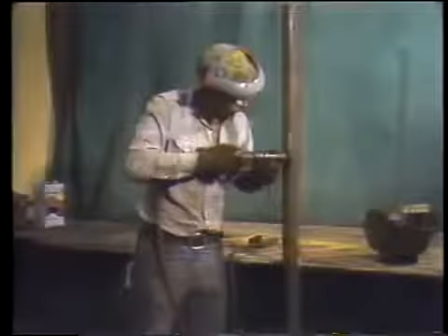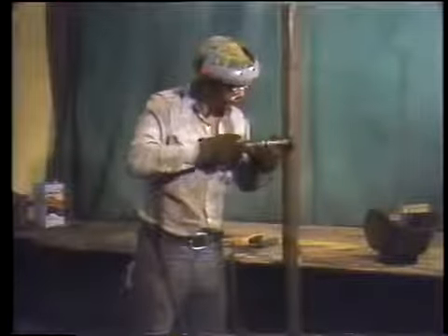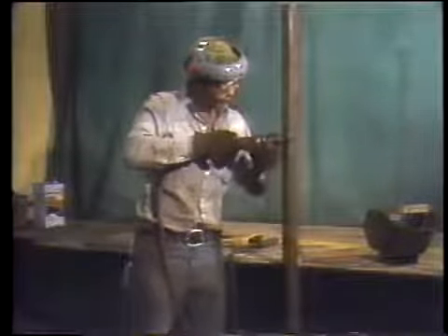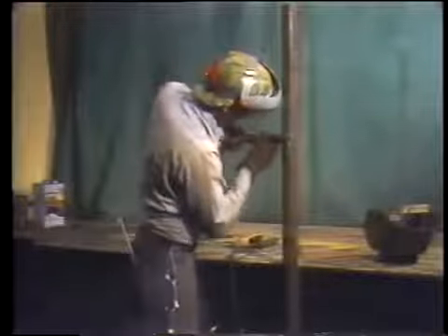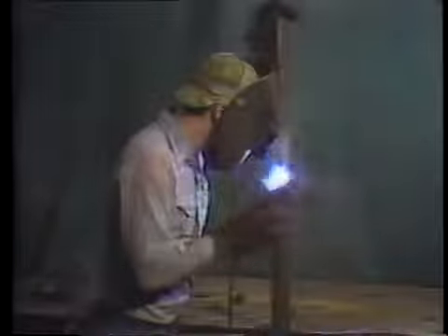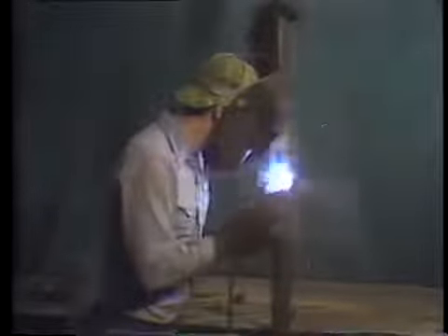Clean the area to be clad so it's free of rust and other deposits. Hard deposits or irregularities on the tube must be removed by grinding. The tube should be ground down until the surface is bright. Next, weld metal is applied to the damaged area. Each pass with the weld rod leaves a strip of metal called a bead. The bead is applied lengthwise along the tube.